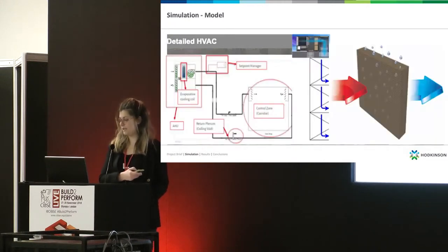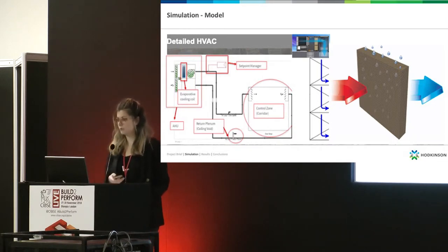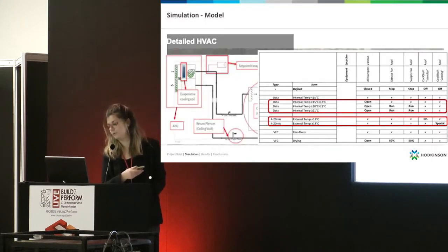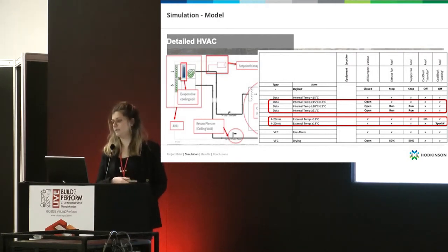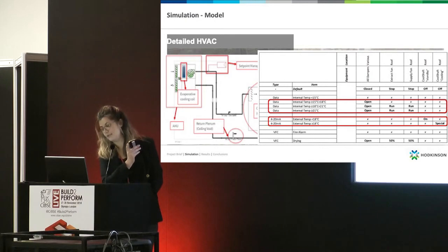And then you can see on the diagram here the airflow path and the system components, with the evaporative cooling fan on the roof, which pre-cools the incoming, hotter air by a water-wetted pad, by evaporating some of that water. And then the cooler air is distributed in the corridors and then extracted through the ceiling void and the staircase from the roof-mounted fan.